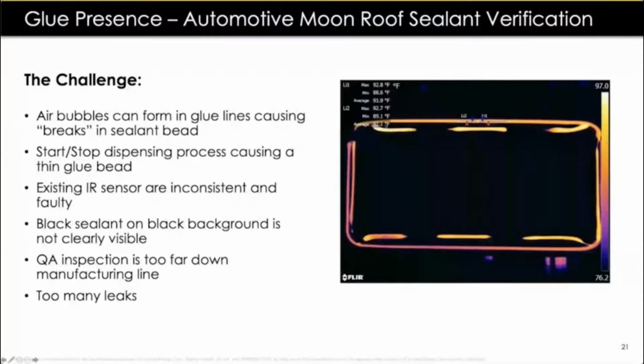So again, with thermal imaging, we map around here saying this is where the adhesive should be present. This is the start and stop, and we want to validate that. A pretty simple process, and it was highly successful.